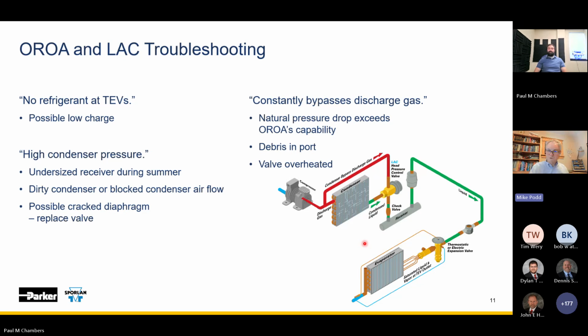If you don't get the refrigerant to flow, you're not going to trip a pressure switch and bring your compressor on. You've got everything matched, but you don't necessarily bring it on, so that's low refrigerant charge. Not having that flooding capacity to keep that pressure up will prevent that flow.